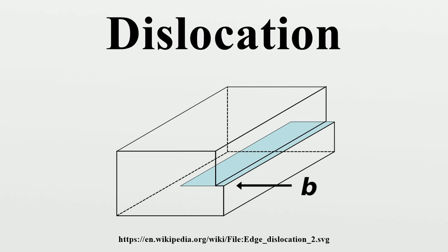In many materials, particularly ductile materials, dislocations are the carrier of plastic deformation, and the energy required to move them is less than the energy required to fracture the material. Dislocations give rise to the characteristic malleability of metals.